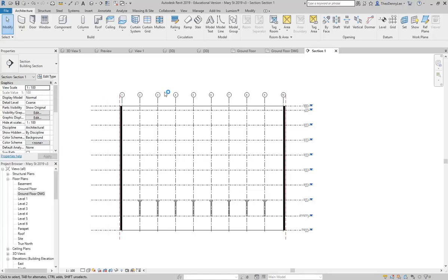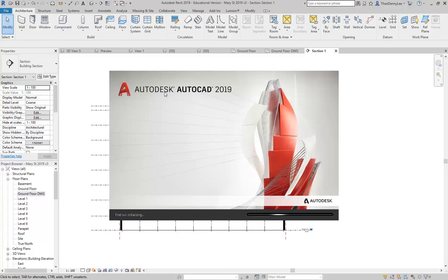So your best friend when you're taking measurements from an AutoCAD file is AutoCAD. Just have AutoCAD open while you're using Revit. If you've been given a stack of AutoCAD drawings, it's the easiest way to measure. Because I see people printing them out and then scaling off the printout and then getting the measurements wrong. And if you've got the AutoCAD file, you may as well use it.